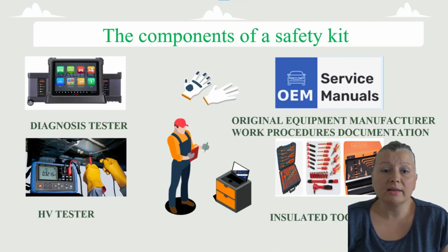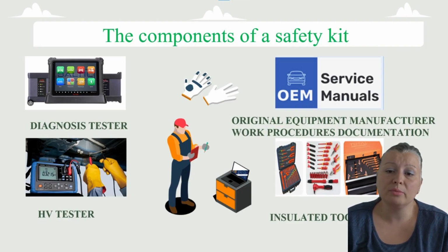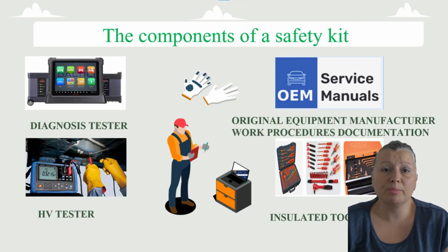Moreover, you will need a diagnosis tester, an HV tester, original equipment manufacturer work procedure documentation, and insulated toolkits. So we must be very careful because normal toolkits will not be able to keep you safe if you intervene upon electrical vehicles. So stay safe and get special tools.